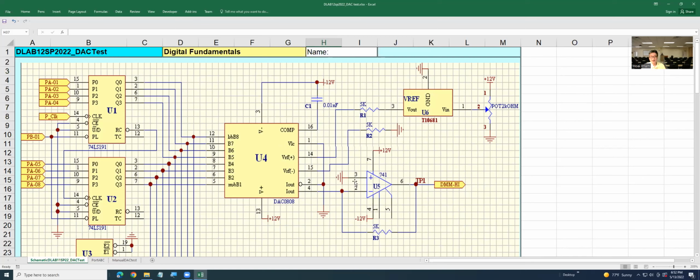And then you get the op-amp 741. For op-amp 741, pin 7 connect to 12 volt, pin number 4 minus 12 volt. So I have to be very, very careful. Okay? The thing is inside the circuitry, you get 5 volt, you get 12 volt, you get minus 12. If they tie together, they cook your board right away.